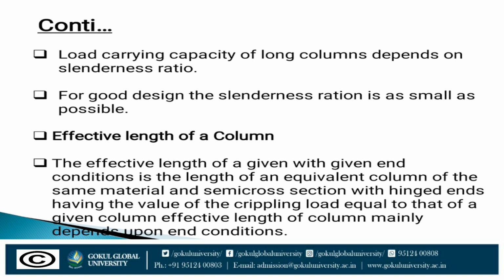Load carrying capacity of a long column depends upon the slenderness ratio. For a good design, the slenderness ratio should be as small as possible.